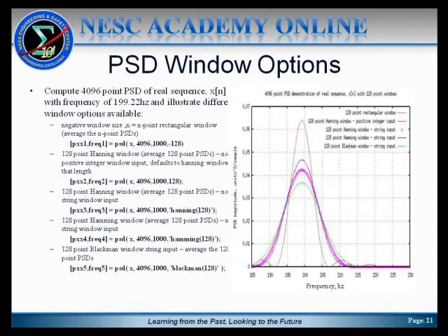Now, as mentioned earlier, these packages like MATLAB and Octave, their PSD functions have lots of window options you can pick from to apply windows to the data as it's computing the PSD. And you saw how powerful that was in the past as far as trying to isolate the particular spectral content so that you don't get these issues of spectral leakage, or the power of the waveform being shared by adjacent sinusoid basis frequencies in the discrete Fourier transform.